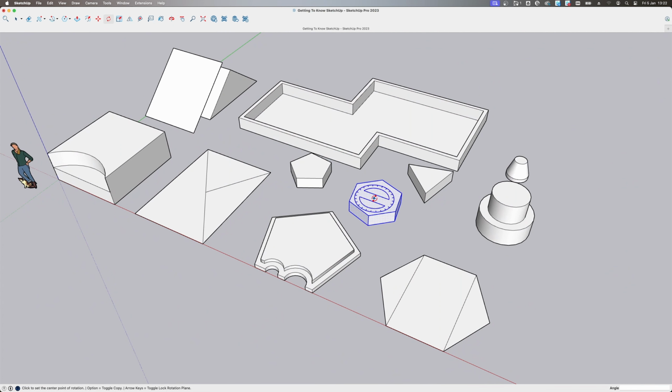Here we have the Rotate tool. The Rotate tool lets you rotate geometry to any angle. Click to select the plane that you want to rotate on. If your plane is perpendicular to an axis, you'll see the colour change to either blue, red or green. Click to select your angle's vertex. Move the cursor in the direction of your rotation and click to confirm.